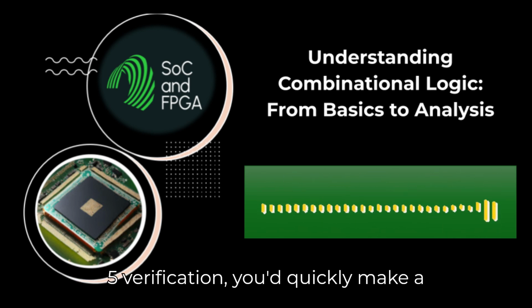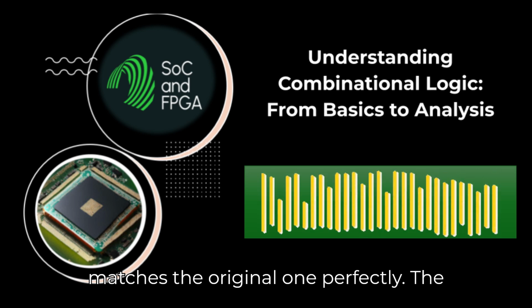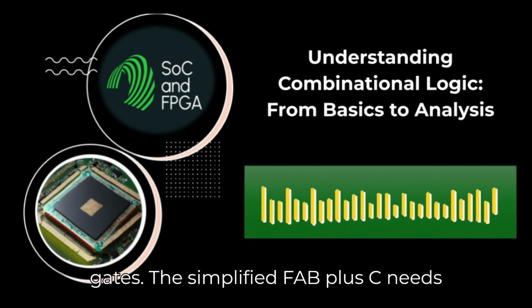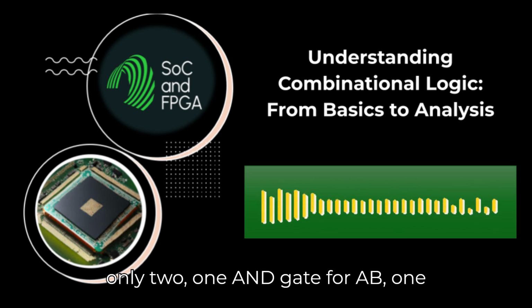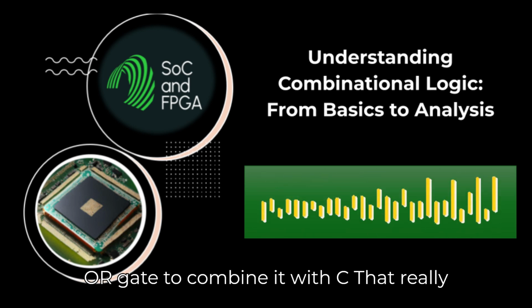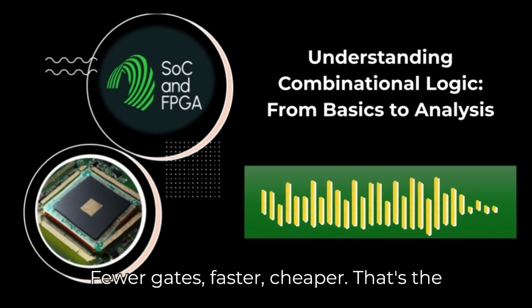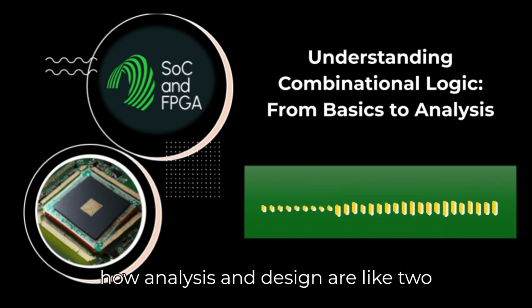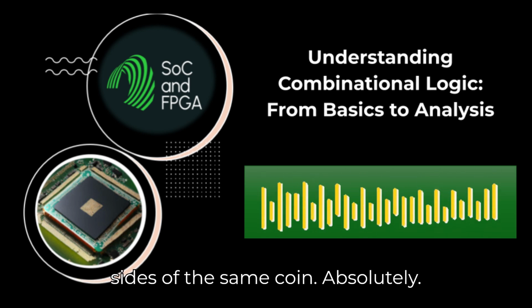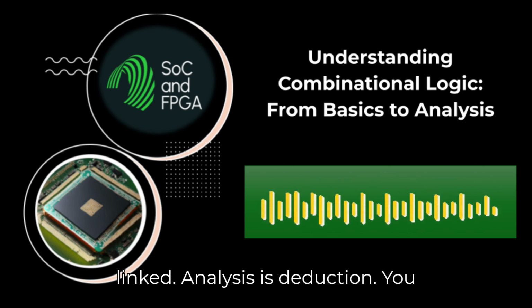And for step 5, verification, you'd quickly make a truth table for F = AB + C and see it matches the original one perfectly. The original circuit might have used, say, 5 gates. The simplified F = AB + C needs only 2: one AND gate for AB, one OR gate to combine it with C. That really drives home the point of simplification. Fewer gates, faster, cheaper. That's the goal. And this whole process really shows how analysis and design are like two sides of the same coin. Absolutely. They're inverse processes, totally linked.